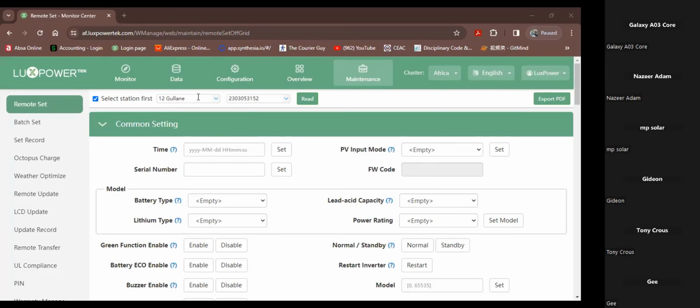You can do that, and what you can do then is take, since you put up your 6.6 kilowatts. Now, I never advise clients to use the full range, purely because you must remember that our MPPT can take 6.6 kilowatts, but we've allowed for the peak power at 6.6.